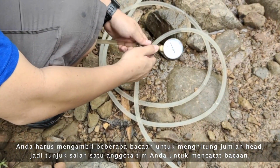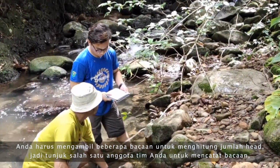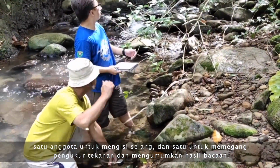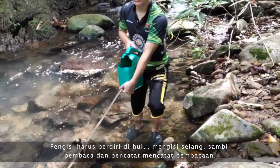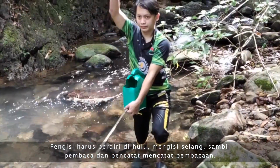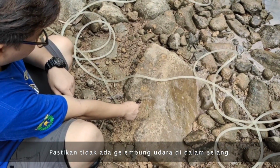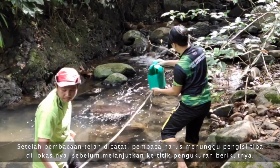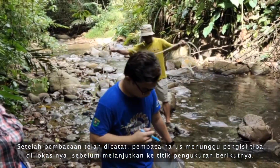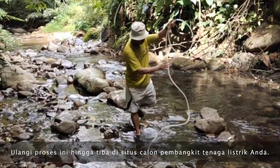You will have to take multiple readings in order to calculate the total head, so assign one member of your team to note the readings, one member to fill the hose, and one to hold the pressure gauge and announce the reading. The filler should stand upriver, fill the hose, with the reader and note taker recording the reading. Ensure there are no air bubbles in the hose. Once a reading has been noted, the reader should wait for the filler to arrive at his location before proceeding to the next point of measurement. Repeat this process until arriving at your prospective powerhouse site.